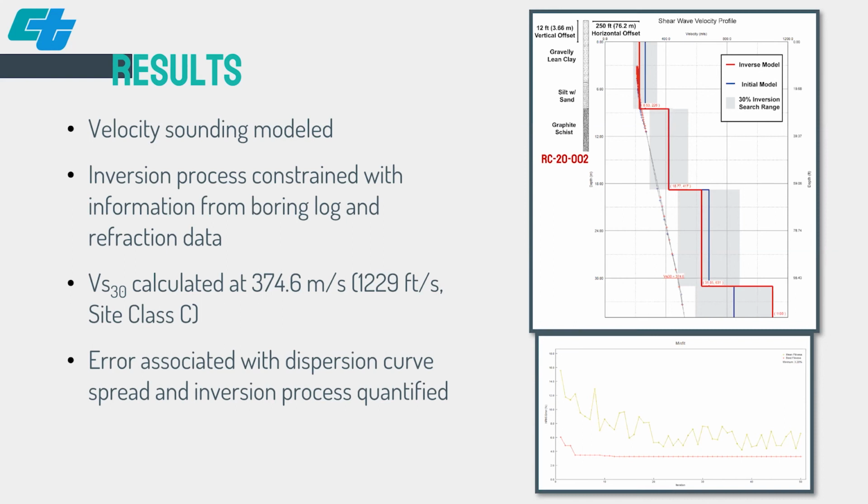This emphasizes the value of a priori information or data from other methods. In this case, we were able to obtain VS30 using MASW data exclusively due to the stiffness of bedrock. However, generally, passive measurements should be utilized to confidently investigate below 20 meters, according to the Inter-Pacific guidelines.